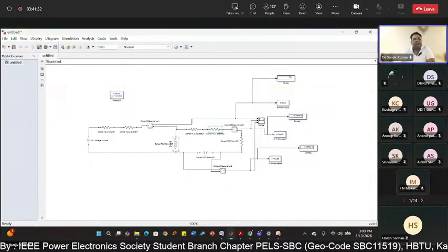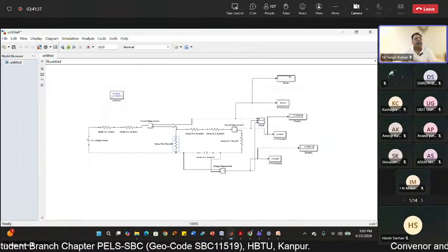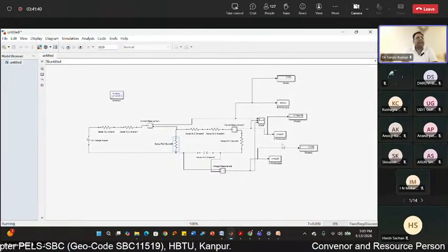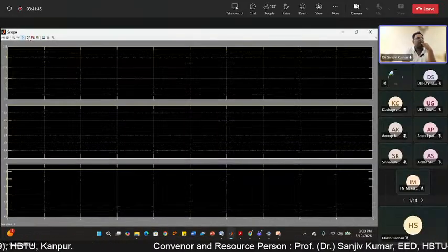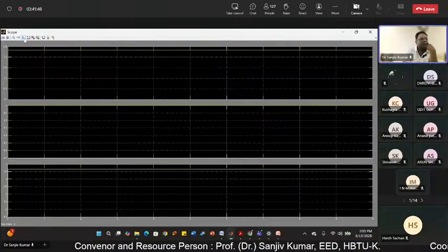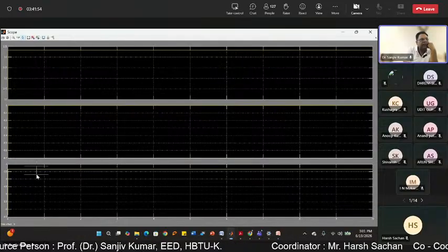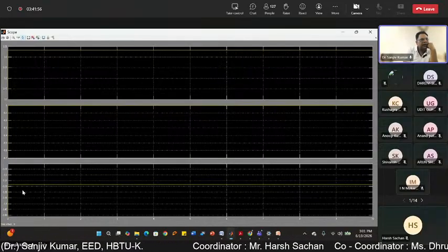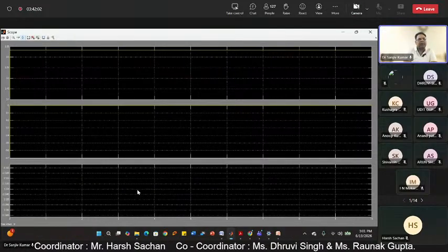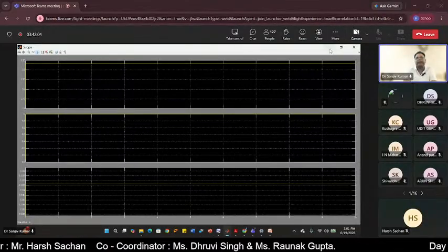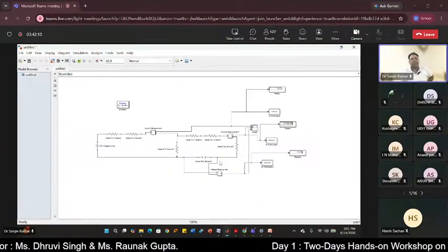The circuit is not the problem, the values are the problem. Let us make all resistive, right? Now you can directly see the response will be straightforward. There is no oscillation or anything like that. You just see the voltage value is minus 0.3, and throughout it is fixed. It is negative. Why is it negative? Because the current would flow like this.